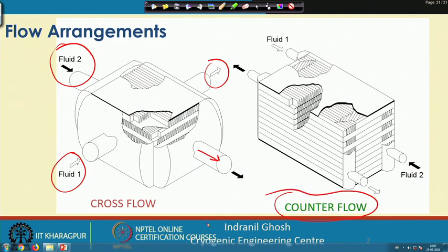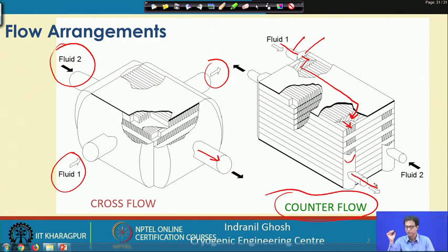seen that we need a distributor to distribute the flow. I mean, from where it is coming, this is the nozzle, then we have the header, then we have the distributor to allow the flow to come in and then get distributed. Finally, this moves out from this distributor fin assembly, and finally it gets collected in this header and the nozzle and moves out.